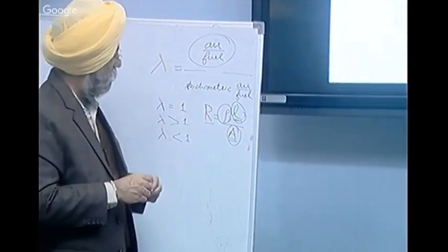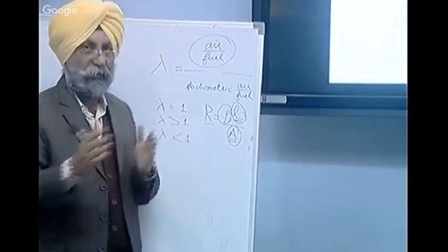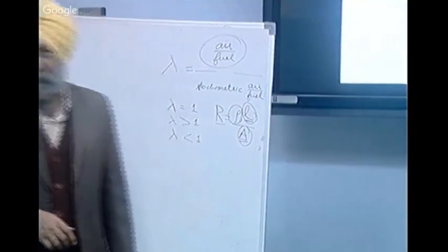That is the difference between a piezoresistor and other normal pressure sensors. Because MAP sensors and other differential pressure sensors in automobiles have to be very small, we cannot rely on changes in dimensions. We rely on the change in piezoresistivity.